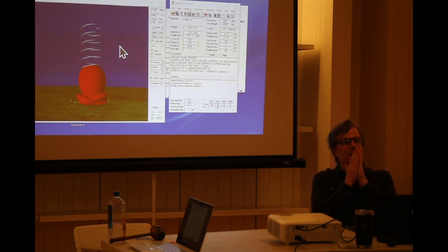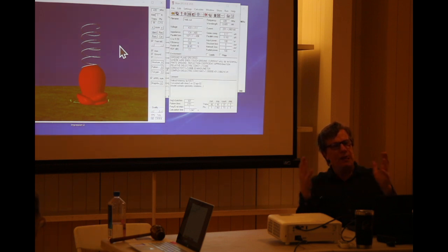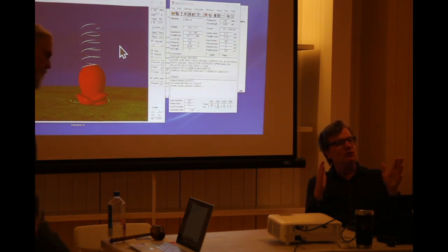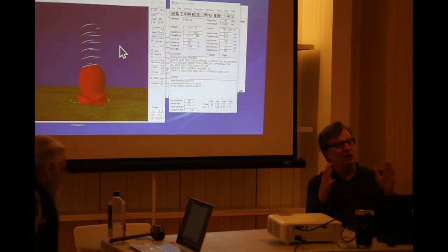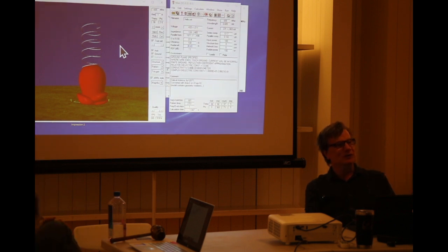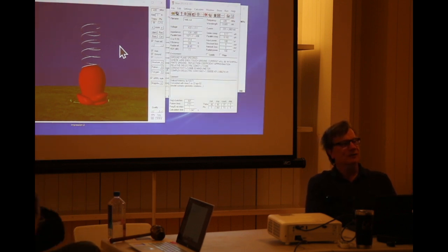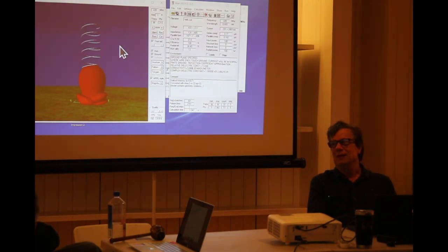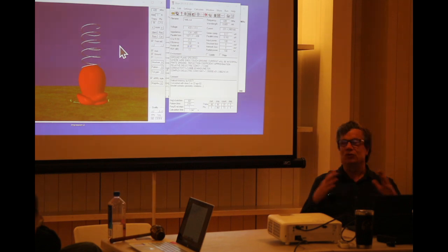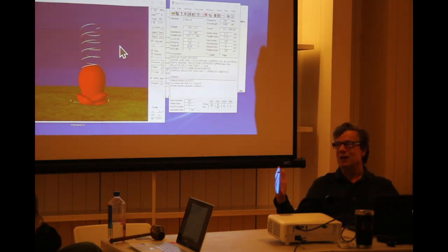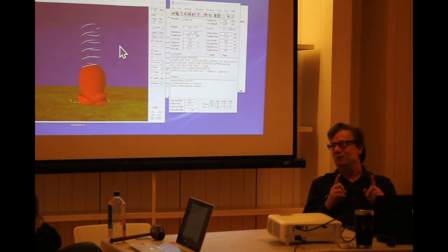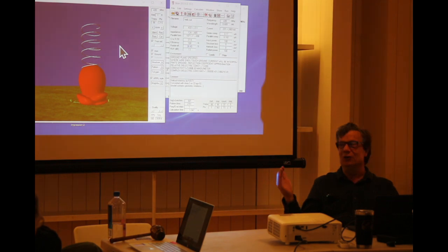Okay? Here's another thing. If you're building a multi-phase array using multiple elements, what gives you a cleaner pattern? Wide spacing or narrow spacing between elements? In between. Actually, the closer you are, the cleaner your pattern is going to be. You start getting more side lobes as you move farther and farther apart. But the gain of your main lobe becomes greater. So to get a cleaner pattern, you move in.